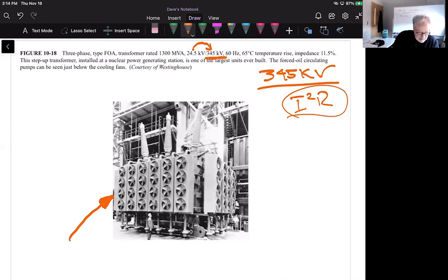Some big transformers are designed to have multiple ratings depending on the type of cooling that's used. Okay, a transformer may have a triple rating of 18,000, 24,000, 32,000, depending on whether it is cooled by natural air, forced air, or some sort of forced circulation. So you can actually increase the operating parameters of the transformer based on what type of cooling that you use.